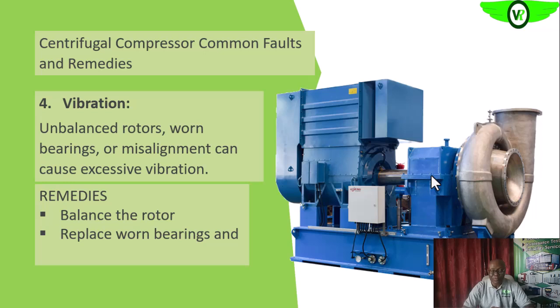So we also want to replace worn bearings once we see that the bearing is the cause of the excessive vibration. So the bearing vibration, we also see in the bearing frequency range in our vibration spectrum. But if we are looking at journal bearings, okay, that we will see in the sub-harmonics, increased vibration in the sub-harmonics and harmonics in the vibration spectrum.